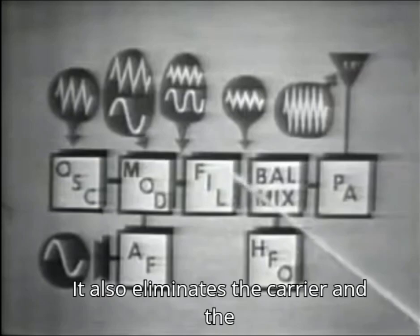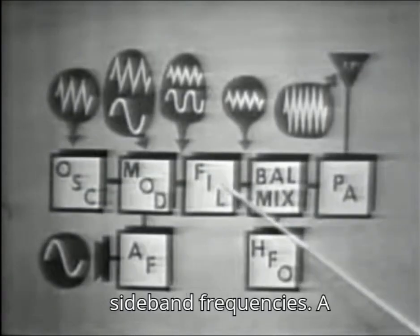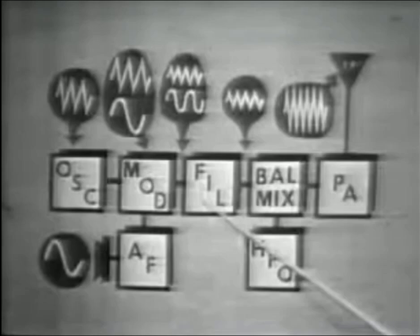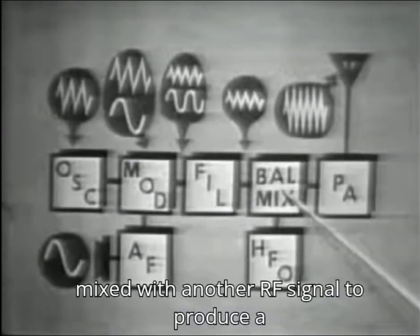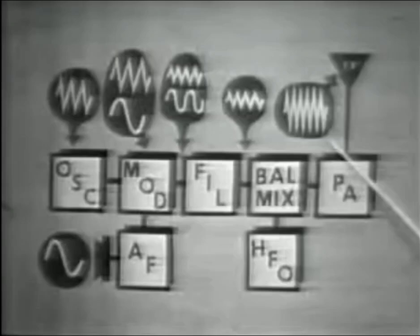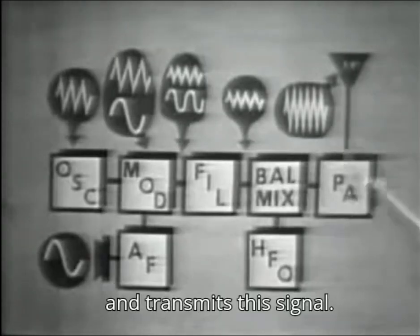It also eliminates the carrier and the audio frequencies, passing on only the sideband frequencies. A sideband filter is designed that selects one sideband and rejects the other. In the balance mixer, the sideband is mixed with another RF signal to produce a sideband of a higher operating frequency. And the power amplifier amplifies and transmits this signal.